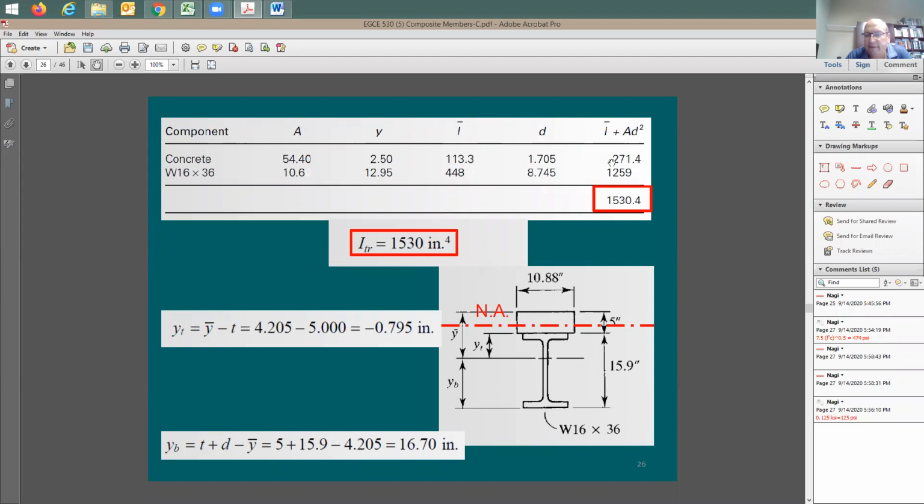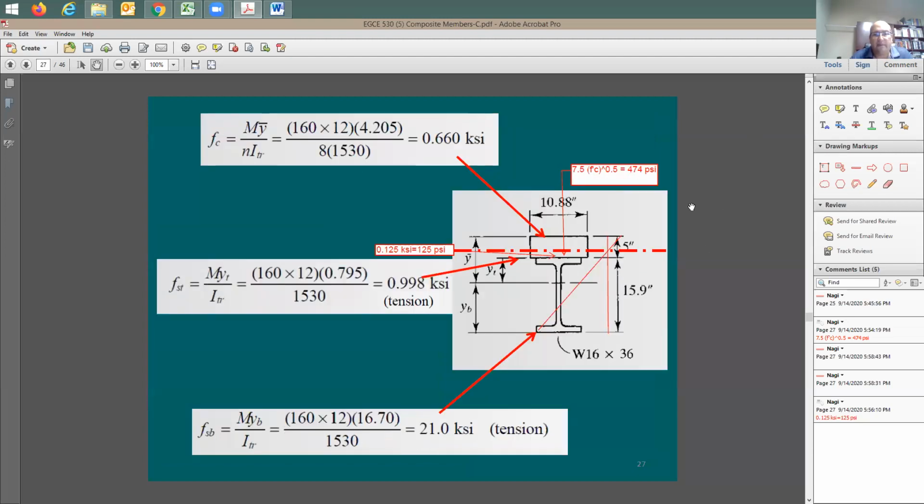So if I bring this to you in an exam or a quiz, I'm going to say, ignore the concrete in tension, or I can say, this is during the design of a steel beam, so you understand what the situation is. Okay, makes sense. Yeah. Thank you. So in design questions, we'll ignore the concrete in tension. And in analysis questions, we will incorporate the concrete in tension. Yes, you'll include this and just leave it like this. And then you make sure that the tensile stress in the concrete is not going beyond this limit, the 7.5 square root of f prime c.